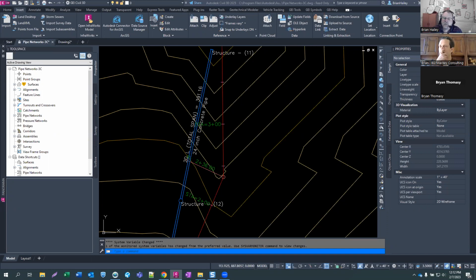If my existing ground surface is in the same drawing as the existing condition site line work, when I XREF that line work into my drawing, I'm also XREFing in that surface. And that surface is not needed for my horizontal control sheets. And so your existing surface should be in a separate drawing than your existing line work. Yep. That way you can bring in just what you need.